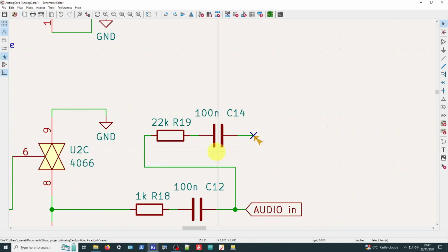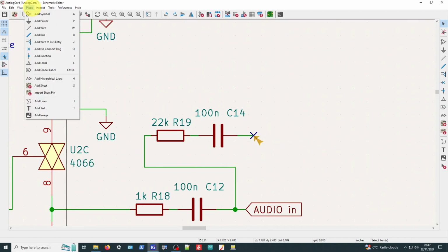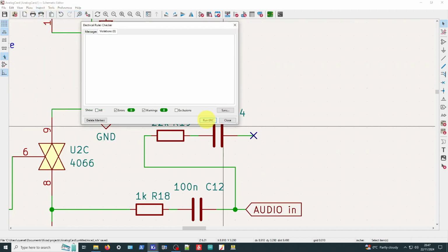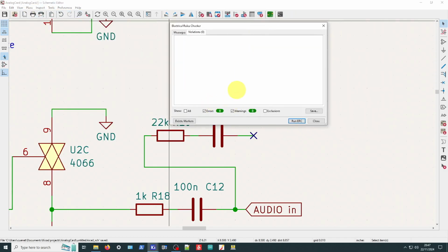It means that there'll be a couple of components on the board, or at least positions for them, and I don't know what to do with the end. Maybe we'll just put it to a pin or something, or a pad on the board that we can solder to maybe. Okay, let's run the inspection again and run ERC. And what do you know, we are error free.